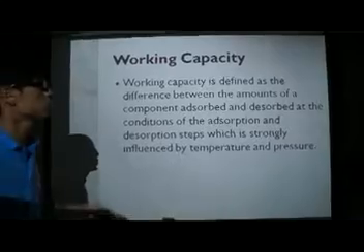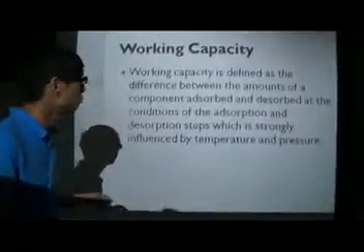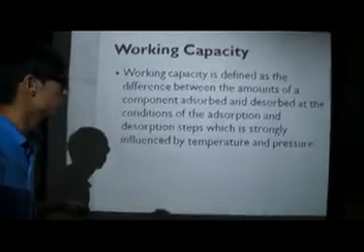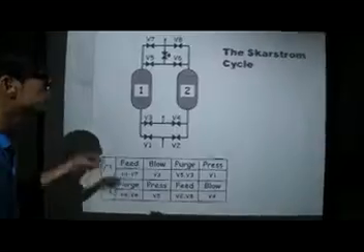Working capacity. Working capacity is defined as the difference between the amounts of a component adsorbed and desorbed at the conditions of the adsorption and desorption steps, which is strongly influenced again by temperature and pressure.